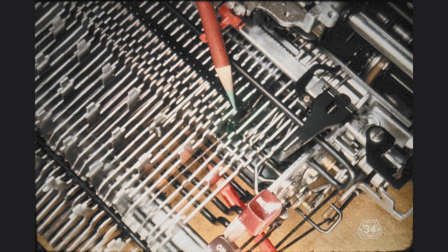The interposer is just what the name implies. It is positioned between the operator, or keylever, green color, and the output mechanism of the typewriter. The lugs at the bottom of the interposers are used to push selector bales toward the front of the machine. The selector bales, in turn, pull the latches which should be filtered out or excluded from the particular print operation.